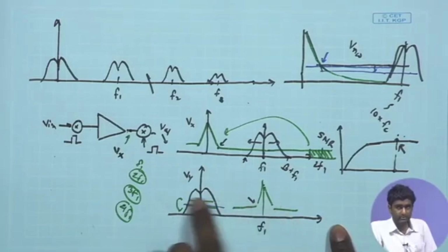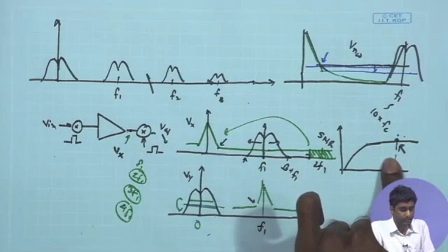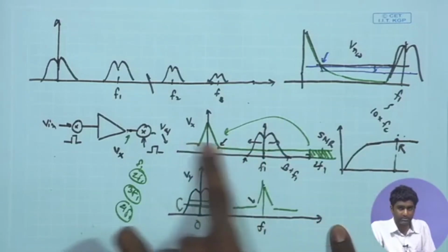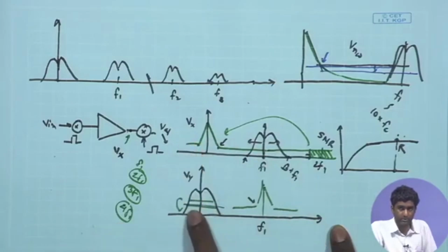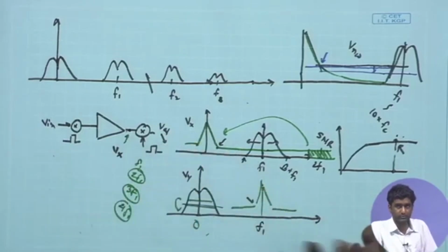Now, this effect is termed as noise folding, where you are folding the high frequency white noise back to the baseband, and which is now overlapping with your desired signal. So, this mandates lowering of white noise also to as low a value as possible, and we have to take care of both these together, white noise as well as the 1/f noise.